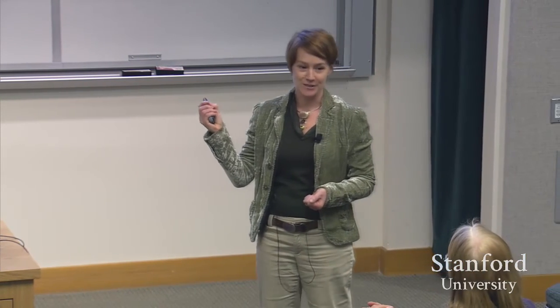And so capture, I know less about capture. There's a woman here named Jen Wilcox in energy resources engineering who does a lot of work on capture. But if you think about what has to happen, you basically need to have some sort of sorbent that will take the CO2 out of the gas stream, and then you have to get the CO2 off the sorbent. So it takes heat, there's some degradation of the sorbent over time. So this is where the big energy penalty comes in, and it can be as much as 40 to 60% energy penalty on the plant for CO2 capture. So it's a really big number.